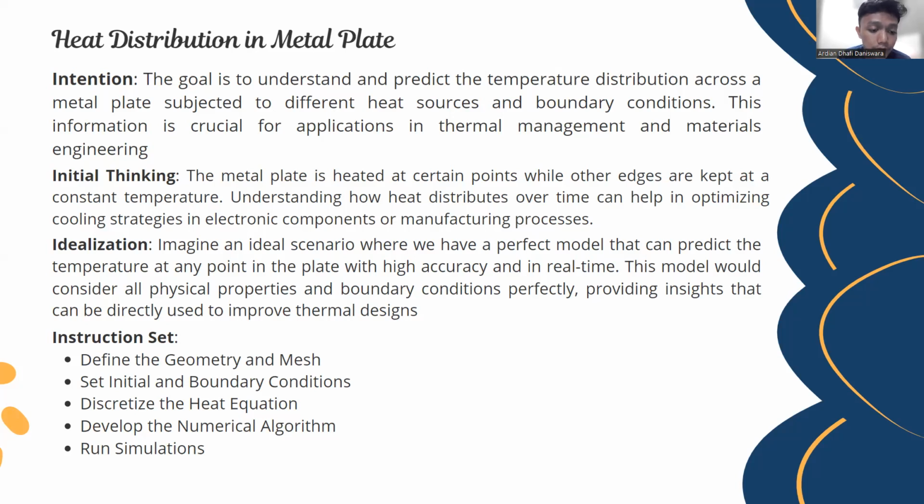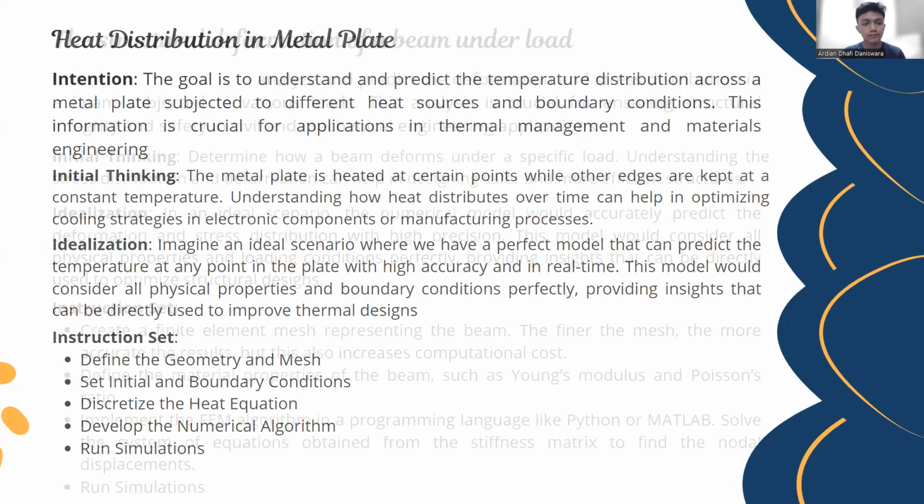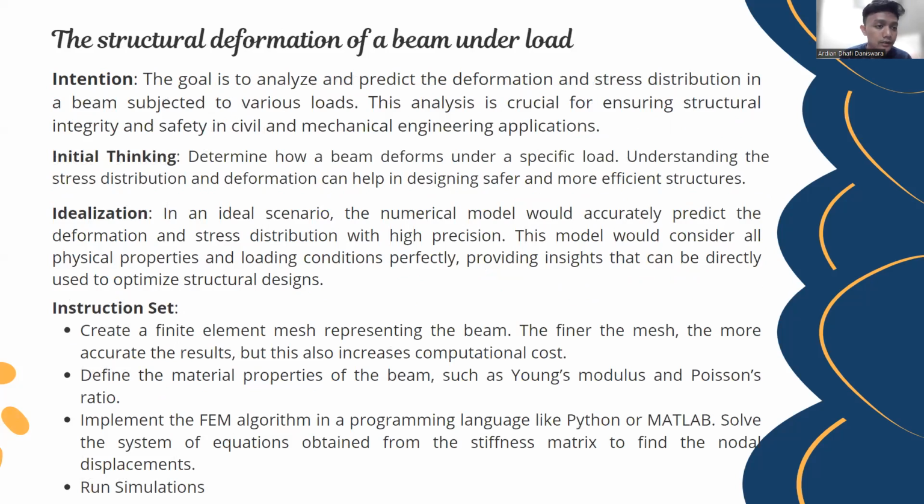First, define the geometry and mesh, and then set initial and boundary conditions, and then discretize the heat equation, and then develop the numerical algorithm. And we can run the simulations. So we continue to the last problem. It's about the structural deformation of a beam under load.